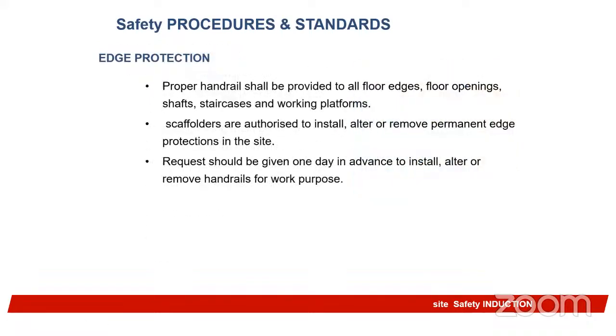Then edge protection. Proper handrails must be provided to all floor edges, floor openings, shafts, staircases, and working platforms. We must always protect the edges, not only for those that are down, but also for those that are up there. So we must make sure that there is a guardrail, a proper handrail where they will hold on to. Even those that are on the ground too.